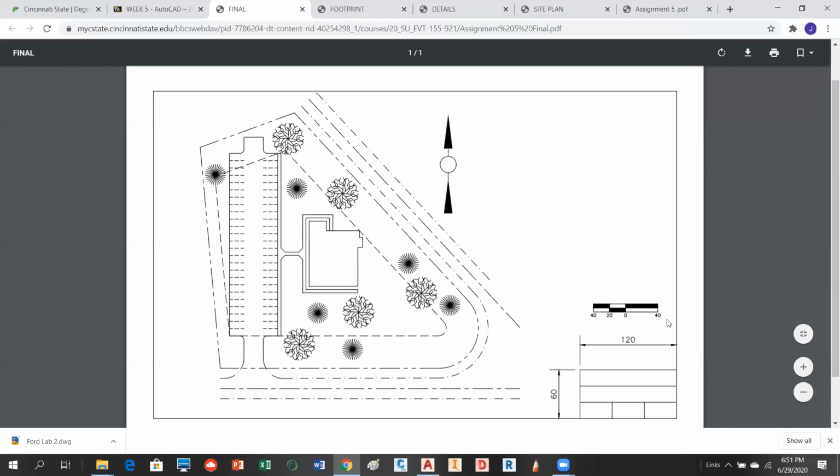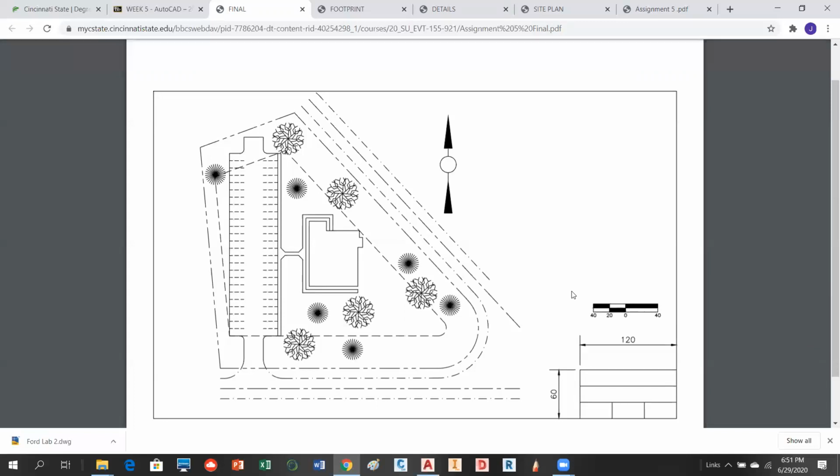As far as drawing it this way, I would probably make it 5 units and 5 units. So 10 units tall, split by 5s. And then you can fill those in with wide polylines. That's a wide polyline, and that's a wide polyline. So that's the easiest way to make that, okay? Any questions on that?